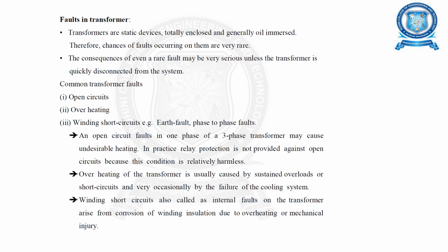Transformers are static devices, totally enclosed and generally oil immersed, and common transformer faults are open circuits, overheating, and winding short circuits. Open circuit faults in one phase of a three-phase transformer may cause undesirable heating. Overheating of the transformer is usually caused by sustained overloads or short circuits. Winding short circuits, also called internal faults on the transformer, arise from corrosion of winding insulation.